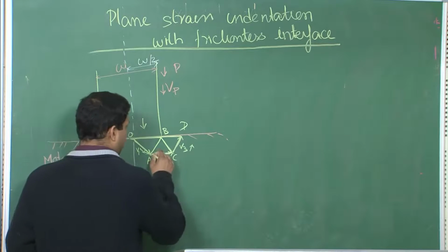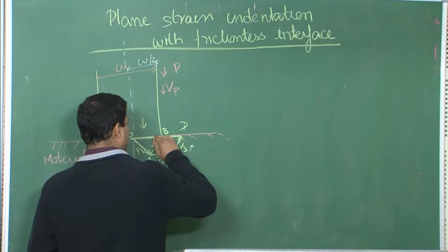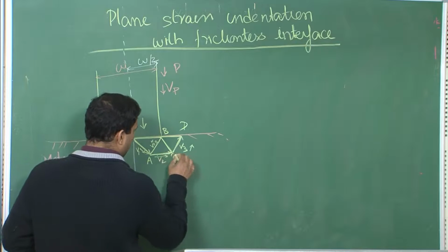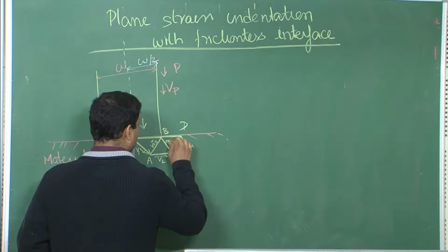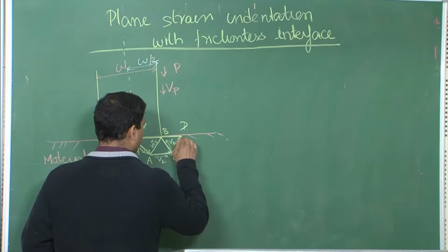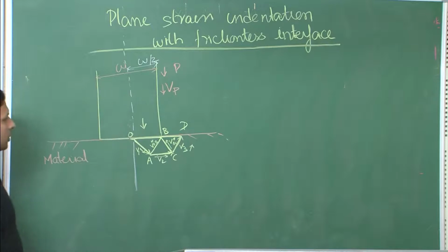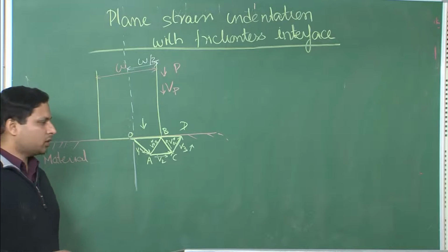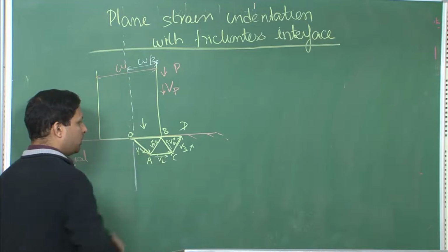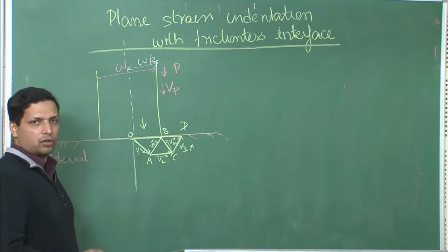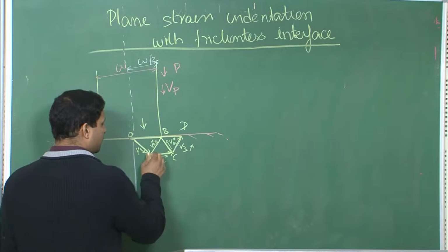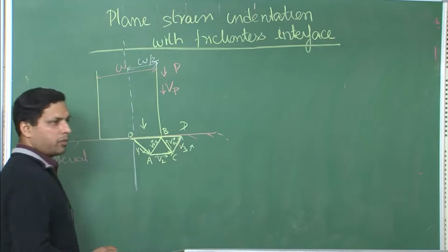And because there is shearing taking place over here, so this is VAB, there is again shearing taking place over here, so this is VBC. So, now we have not only labeled it as the guideline says, we have also drawn different velocities onto this. So, we have the velocity of the moving parts now, and also we have the velocity of the shearing parts.